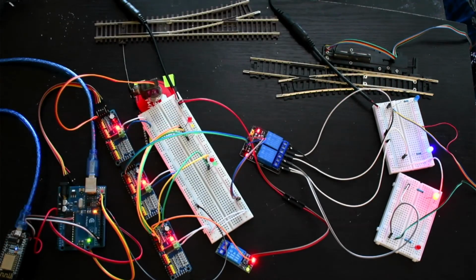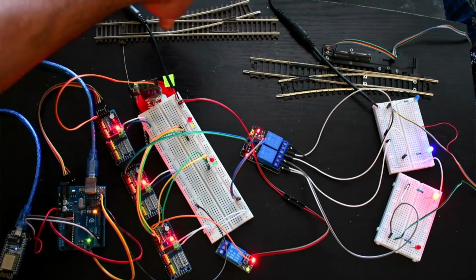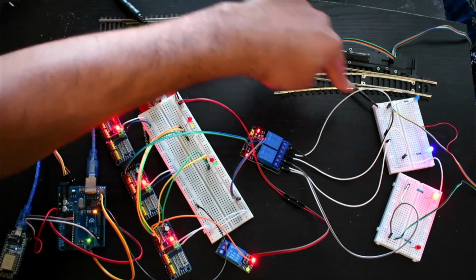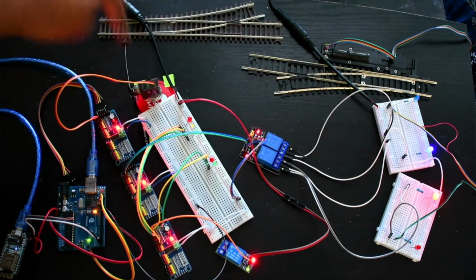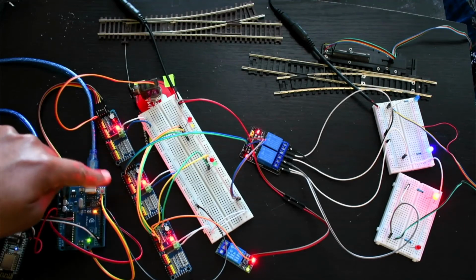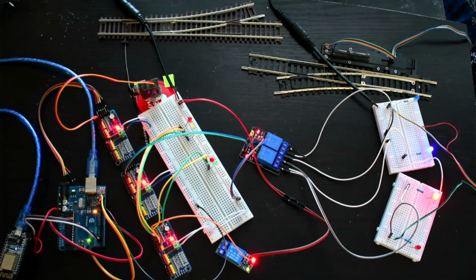So this is how we can do the configuration for servo based turnout and snap based turnout using relay switches in the same node. This chain we can keep going on up to 64 boards, so there is no limit. 64 boards is like 1000-something addresses you will get. So after this, we will go to the light first.